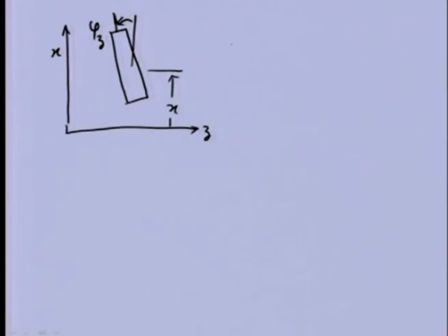In the right hand, this particular angle I have taken in the positive direction, that is z to x. The tilting I have taken in the positive direction, also the linear translated displacement in the positive direction. Now, because we have removed the shaft, there will be an elastic force opposite to the x direction, f x. Apart from this, there will be a moment which will oppose the tilting motion.